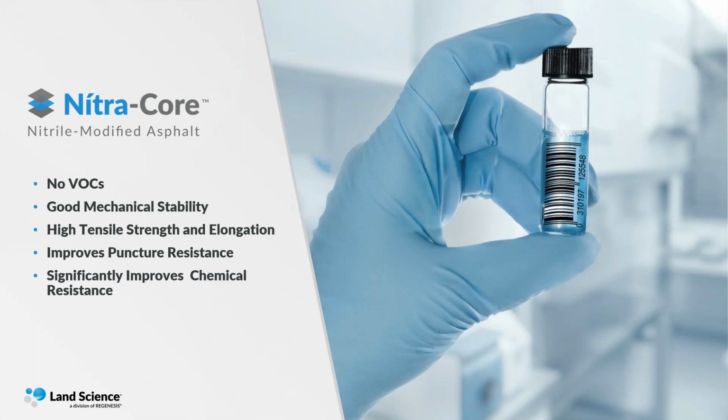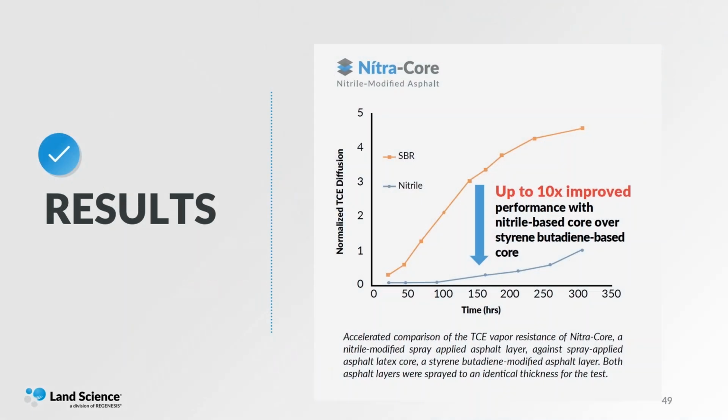So one of the other aspects of MonoShield that I want to get into, it's a highly chemically resistant barrier, the mono base, because of the aluminized metallized film that is infused into the barrier. But then we also implemented a new spray apply nitrile modified asphalt core called NitroCore. It's got no VOCs. It actually has a higher tensile strength than our previous latex asphalt, and it significantly improves chemical resistance. As you can see here, the NitroCore provides up to a 10 times more chemical resistance than the standard styrene butadiene based core that has been previously used on the latex sprayed asphalts.